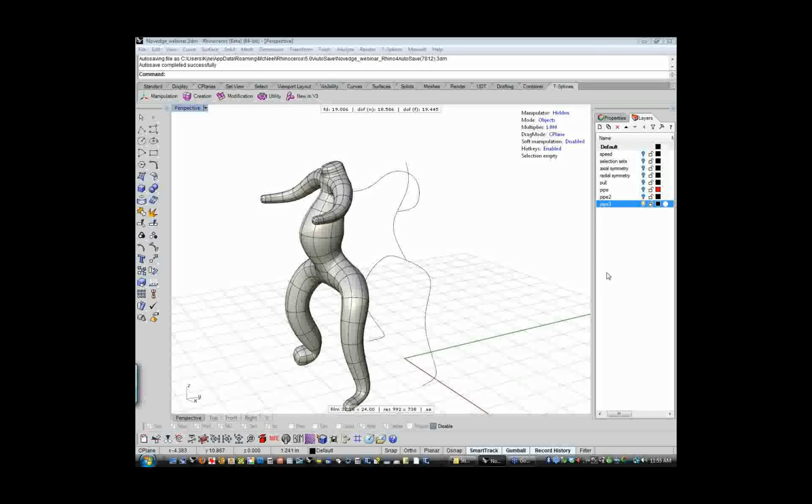The fix for that would be to go through and really fastidiously line up all your alignment handles. But I think the actual answer is that you need more faces around. Instead of it just being 4 faces around, I think you need 5 or 7 in order to create a round symmetric object and have it make those transitions correctly.